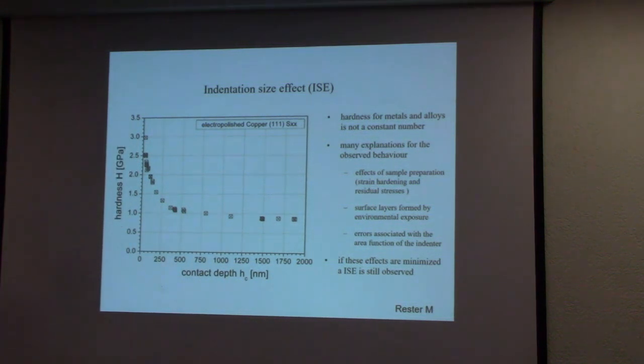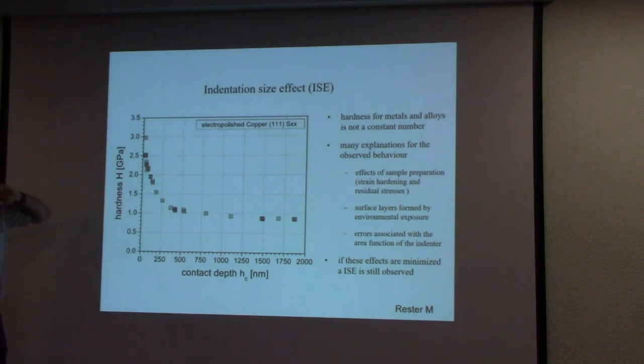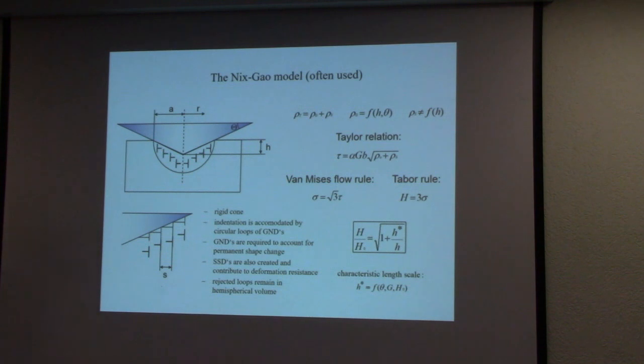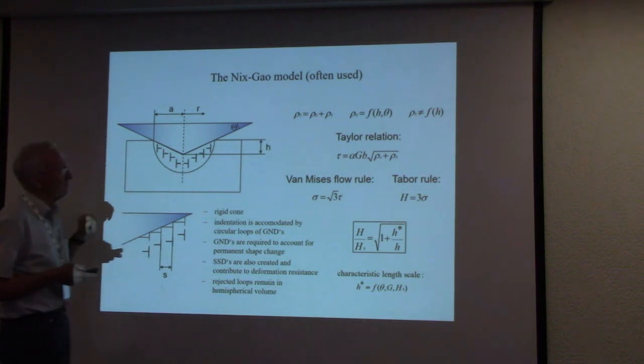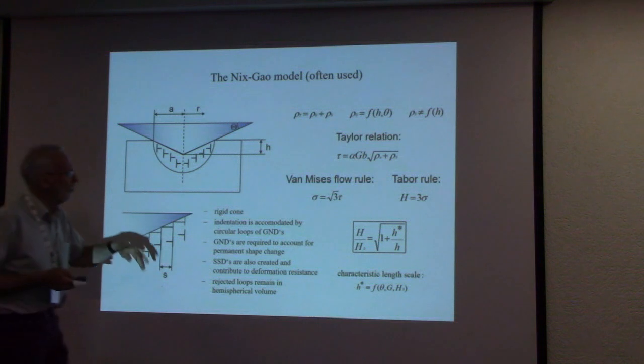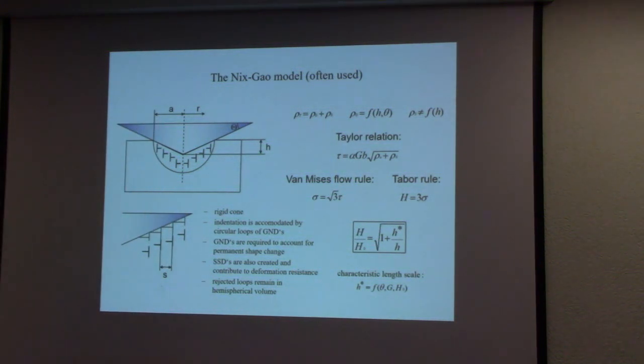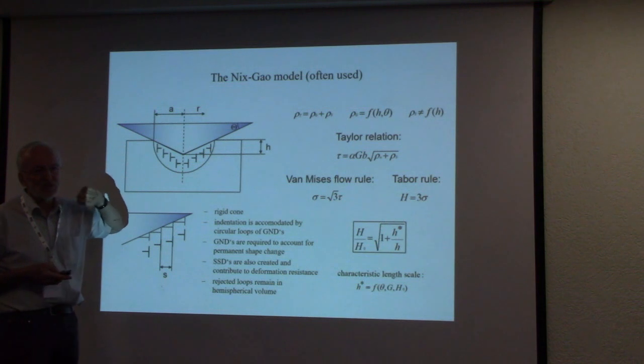We have to use a logarithmic plot in this area. So the standard, most used concept to explain this size effect was also the strain gradient theory. This results in the so-called Nix-Gao model. And I always had some doubt that this really works for these extremely small dimensions.